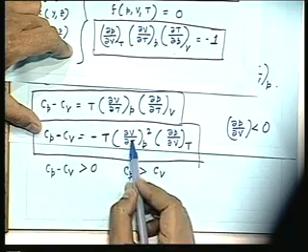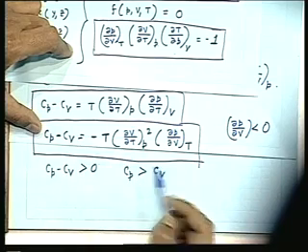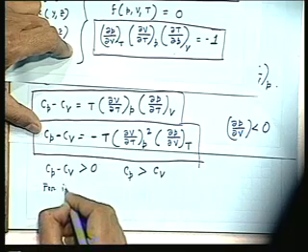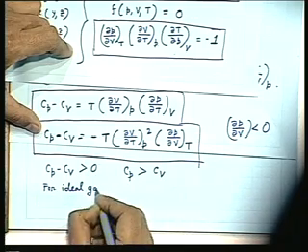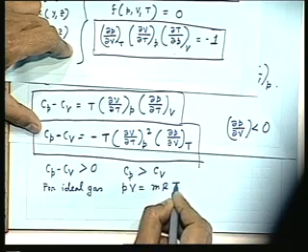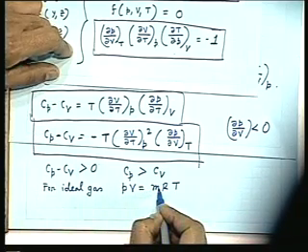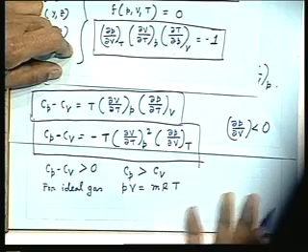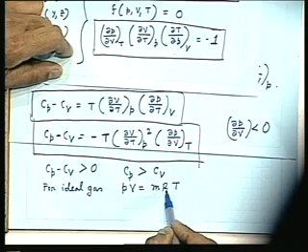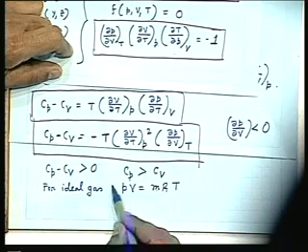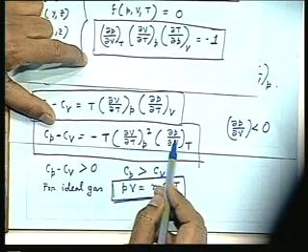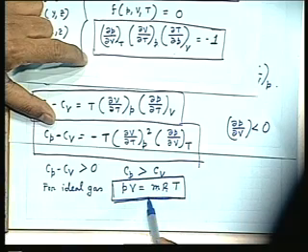We know the equation of state is the equation between P, V, T. For example, in the case of an ideal gas, which we will discuss afterwards, the equation of state tells that P into V is m into R into T. For an ideal gas of mass m, the pressure of a closed system into its volume equals m into R, a constant known as the characteristic gas constant, into T. So in this equation, if we use this as the equation of state and find out these parameters del V del T at P, then it becomes a very simple exercise.